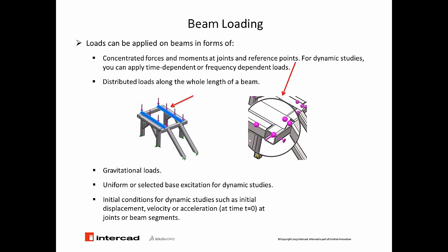Loadings are all new features when you are using a beam element. You might use any face in a solid or shell approach to apply your loads, but in beams you can have concentrated loads and moments on the joints or reference points. Well, in dynamic studies you can have time-dependent or frequency-dependent loads, or you can have a distributed load, as you can see in the other picture, which is acting on the whole length of the beam.